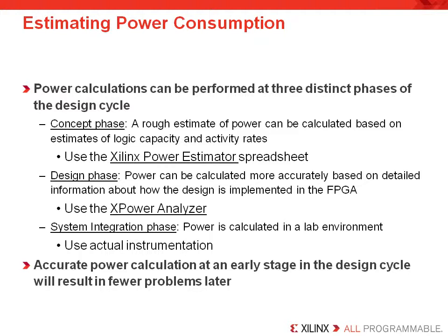placed, and routed designs. So all the true information, all the device resources, all the routing that's necessary for your design is known. So this power estimate is much better than the one you would get with a Xilinx Power Estimator. And finally, of course, you can go to the lab after you've built your FPGA and program the FPGA and do an actual test with instrumentation in the lab to determine your actual power used.